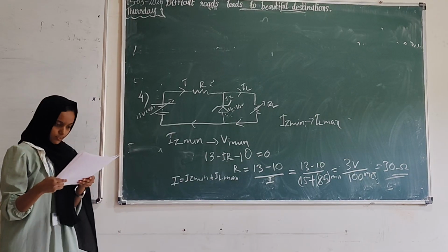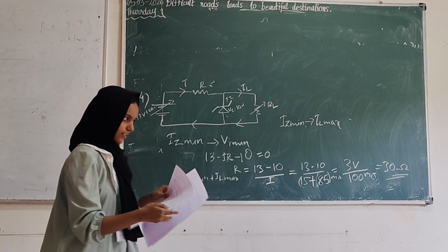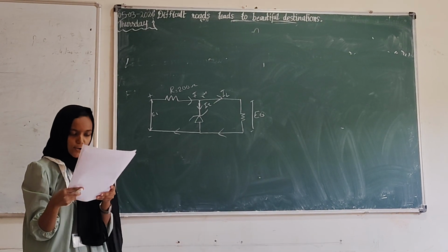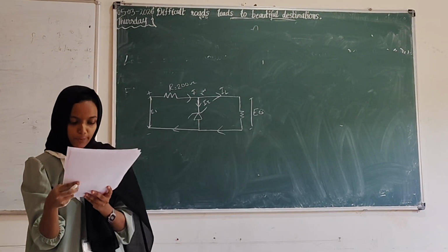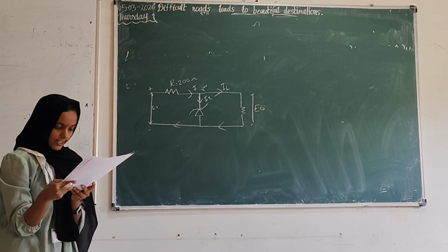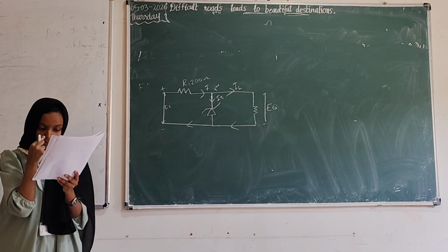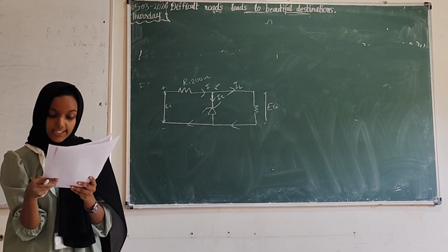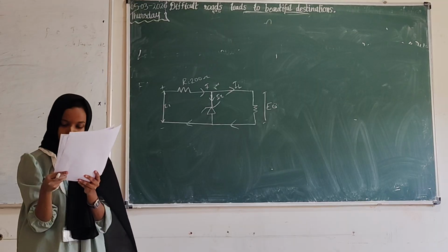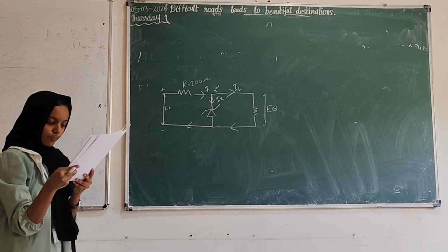Done. Fourth question, and moving to the last question. The question is: over what range of input voltages will the zener circuit shown in the figure maintain 30 volt across a 2000 ohm load, assuming that series resistance R is equal to 200 ohm and zener current rating is 25 milliampere.